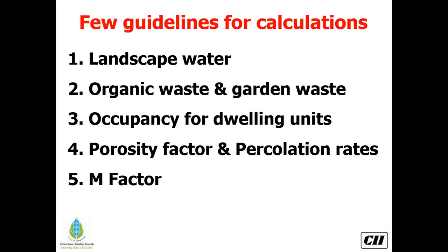Please note, irrespective of the plant species, water requirement should be arrived at, and this should be met for the first year. Projects normally claim that in the total landscape area, say for example 1000 square meter, in which 90% is drought tolerant species and 10% is turf species, since they are proposing drought tolerant species, there is no water requirement.